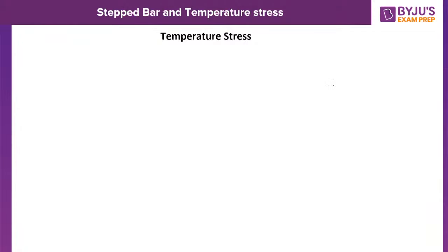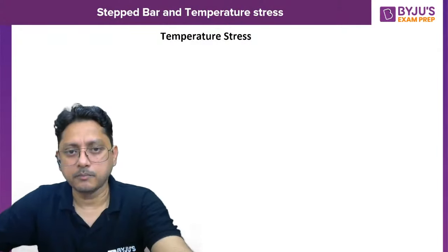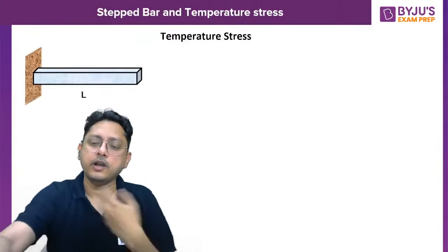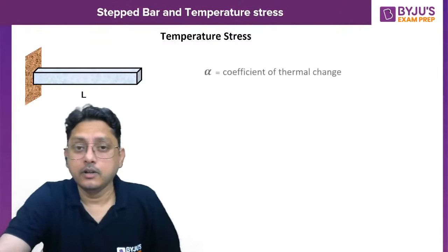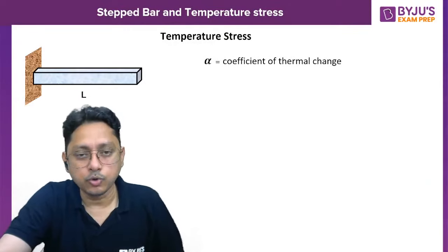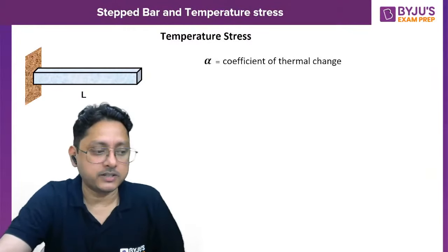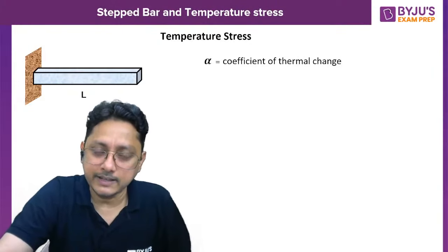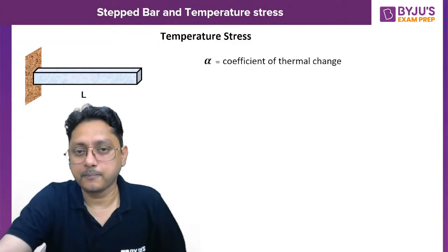Now, what about the temperature stress? How to deal with the temperature stress problem? See, first of all, if you have any block, suppose a cantilever beam, if you are going to increase the temperature, you know that the block is going to get extended. No? There will be expansion. If you don't have any restraining position, a free expansion will be there for the block.